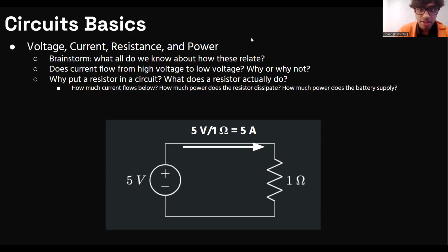Or is there another way you could think about this? Say you didn't have that equation. We could use I squared times R since we found the current. That's another one. But I was going to say more: power, definitionally, is current times voltage. That's the work that a voltage does. The fact that P equals V squared over R or I squared R results from that. So if I wanted to use the logic of P equals IV, how would I apply that? And maybe KVL might be helpful for this.